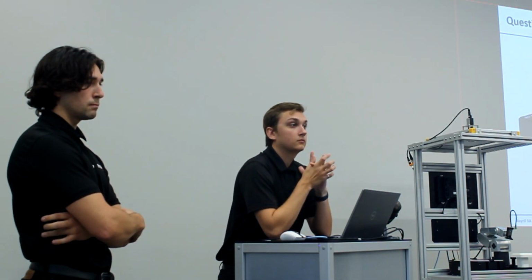So it's going from basically the origin of the AsiCube, and then you just calibrate each robot to that origin separately. Otherwise, if you calibrate 1 robot, then the other robot technically gets calibrated to the first robot's position instead of the AsiCube position. So it's easier to just have them both calibrated to the actual AsiCube itself.